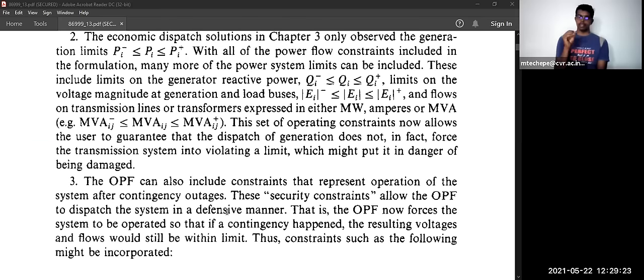Now imagine, in the manual system, some lineman has to come to that particular place, identify the fault, and make a phone call to that particular office. They have to collect whether it is a joining issue or some line to ground fault, everything. They have to take some wires and reach that place. From the office to the fault, maybe 10 kilometers, they have to travel for half an hour or 1 hour. Then they have to climb the poles and correct that transmission line. It will take more time, like 1 hour or 1.5 hours, and by that time we will not be able to receive the power.